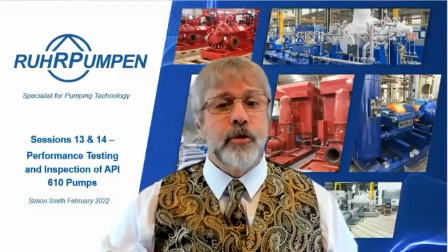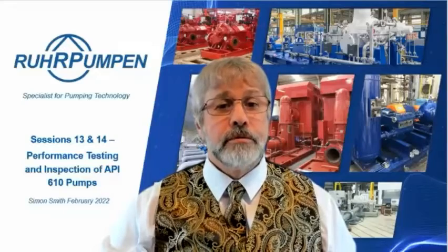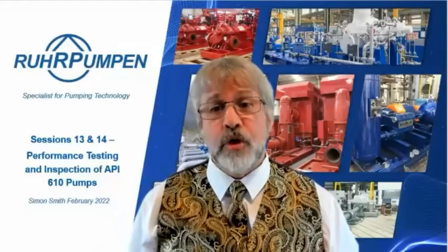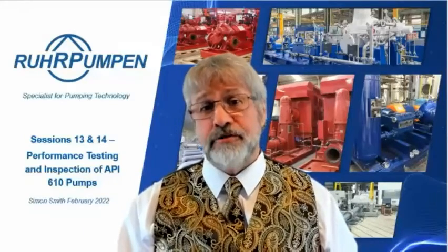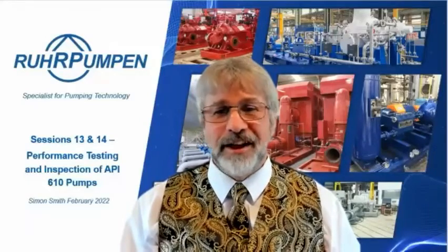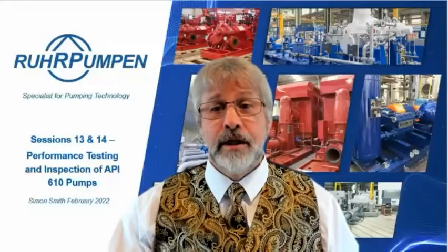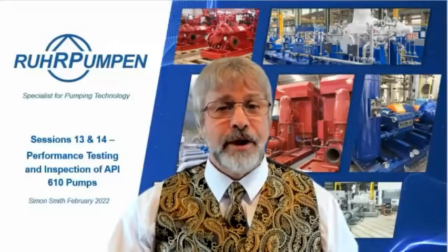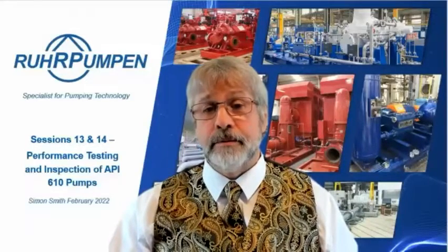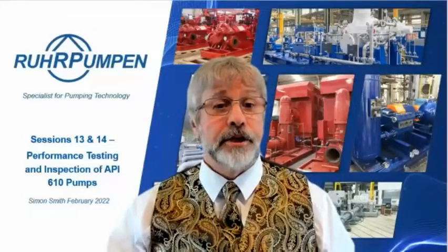Carlos Mallow says, for which component and material do you recommend material certificate 3.2? Super duplex in seawater services? I don't recommend a 3.2 ever. Why would you want one? It just means you don't trust the foundry. So if you don't trust the foundry, I don't know. No, I don't think a 3.2 is ever worthwhile. I can't imagine why you would want to do so. If you're concerned about the possibility that the MTR is wrong, you can always use positive material identification on it.